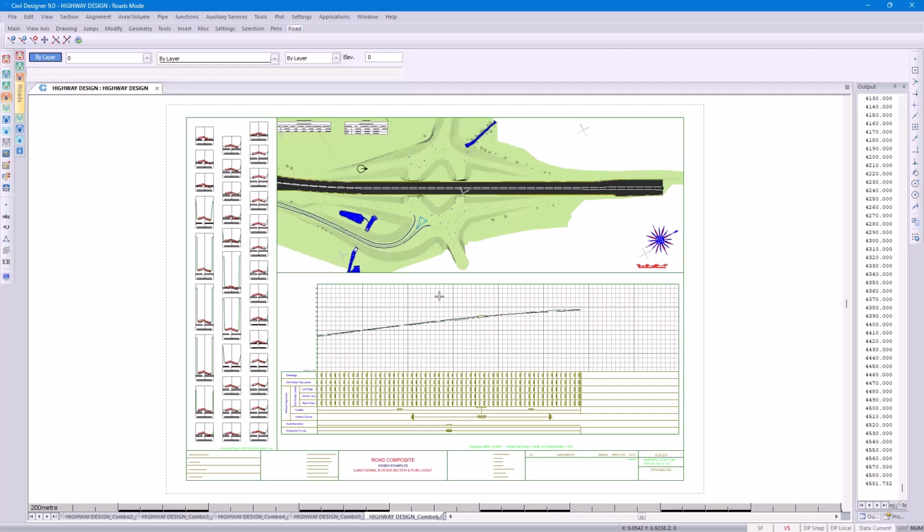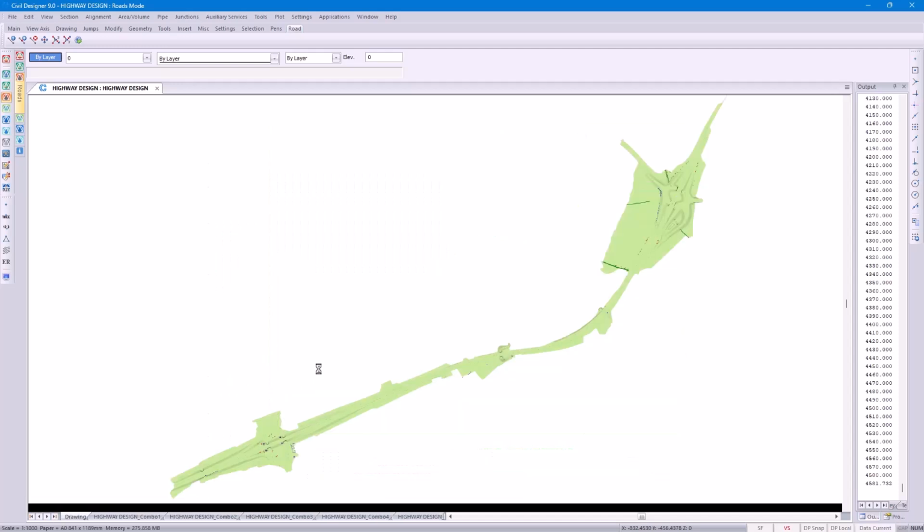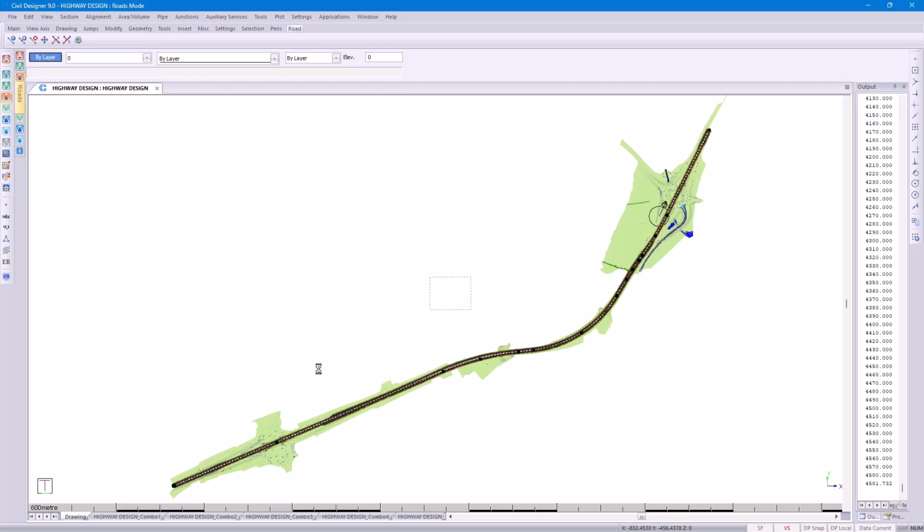That takes a couple of seconds. And then looking at what we have in front of us, we've got the plan layout, or curve and PI lists, the cross sections, as well as the long sections. And you could customize these title blocks according to your project standards. Those layouts will dynamically update as you make changes to your design. When we created this road, I mentioned that you got the use of templates. Let's look at templates in more detail.